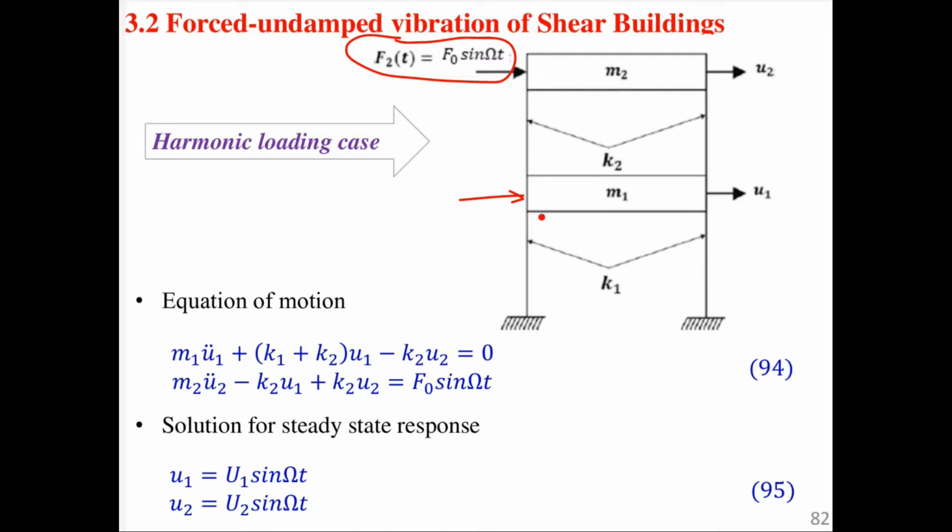Why do we simplify like that? Because when you are doing the real design, you don't just consider this separately. For example, you check a building against, let's say, lateral loads, against earthquake, whether it can sustain. Once that passes, then you go again and do your design with the load combination. We use the load combination, for example, the self-weight, the dead loads, the live loads. So for comprehensive design, we consider all of them.